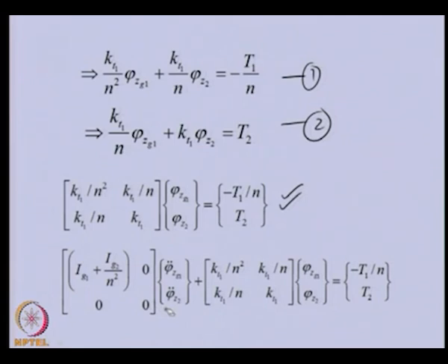That we can add here to get the overall elemental equation for the gear pair. So, this is the inertia term which we obtained earlier, this is the stiffness term, and this is the reactive torque at the end of the shaft. This is the gear element equation, and this is a very important relation. Using this we can analyze the branched system and geared system very easily.